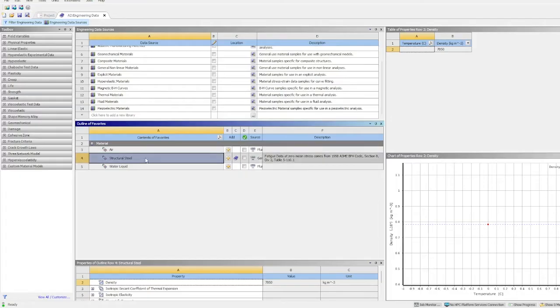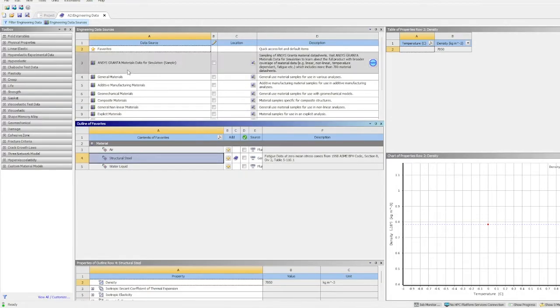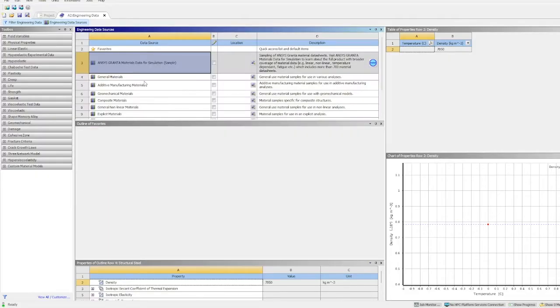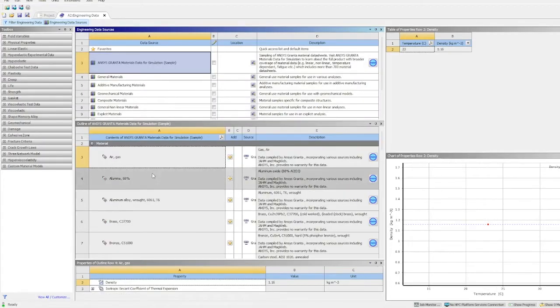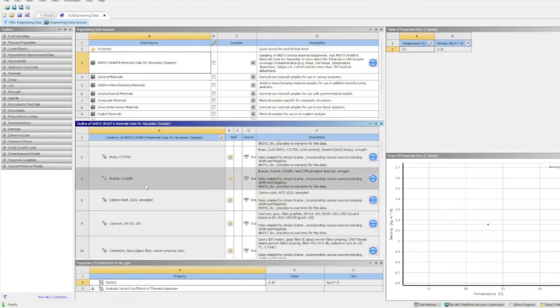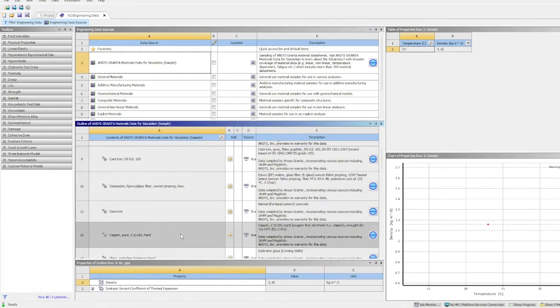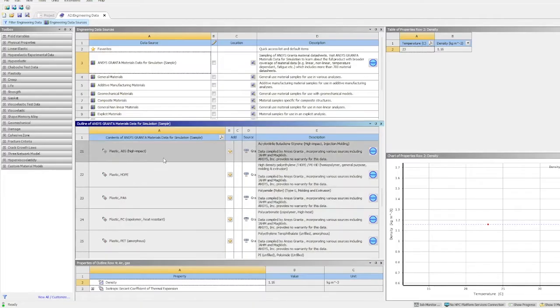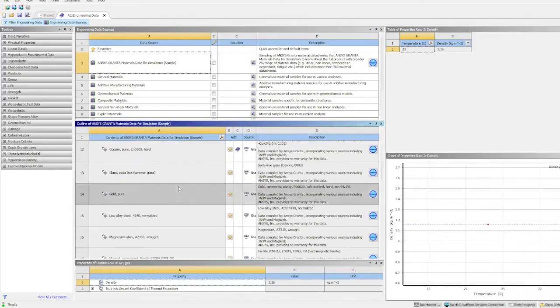I'm going to cheat a little and use the Granta pack that's at the very top. You may or may not have this depending on your version of Ansys. When I double click on that, it'll load up all of the materials down below that I can use. Because we used copper, aluminum, and a polymer in lab, I'll choose those. So I'm just going to choose aluminum and press that little plus mark. Copper, once I find it, and there we go, and press that little plus mark. Then I'm going to add a polycarbonate just because it'd be fun. I know we used, I believe, a nylon in lab, but polycarbonate's a good material to practice with, so I'll throw that in there as well.